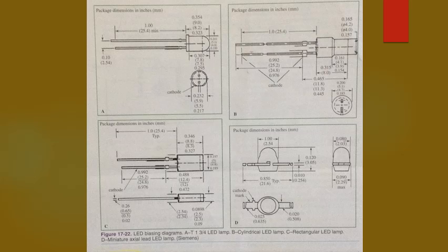Series and parallel rectifier arrangements. Diodes or rectifiers can be connected in series or parallel. This connection is made to improve the voltage or current capabilities of a single rectifier. Connecting diodes in series increases voltage ratings over the value of a single rectifier. Diodes can be connected in parallel to improve the current handling ability of the combination over that of only one diode.